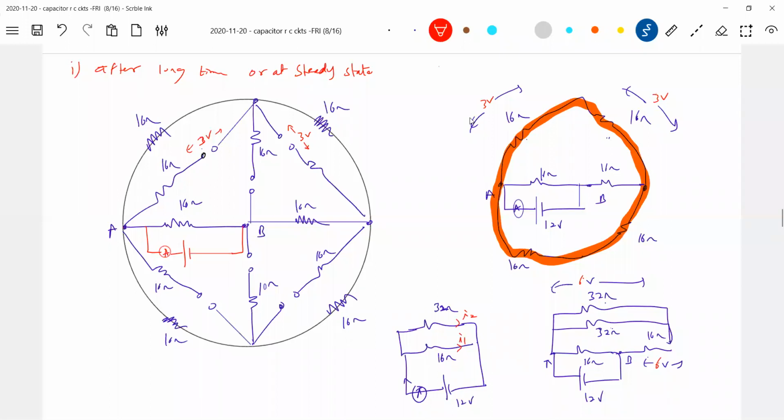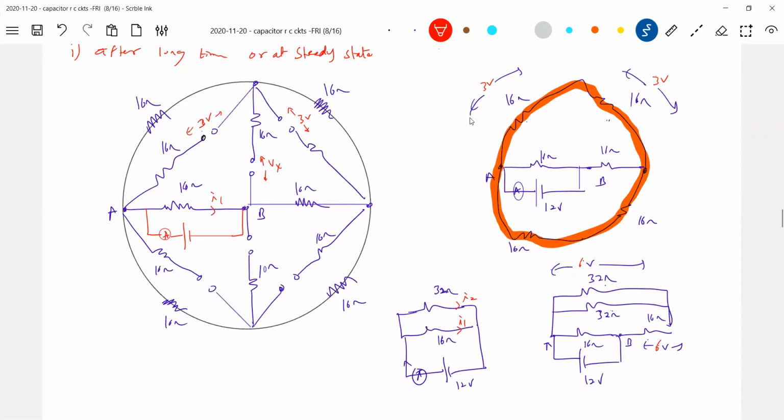It is forcing us to think a lot. That is the problem. Okay, once you know this 3 volt, now you can calculate this particular voltage. Call it V1, whatever you want, you can call this one VA or Vx. Write the loop equation, and you know this current I1. So this should be -3 minus Vx plus 6I1 equal to 0. Solve for, you know, I1 from here, you'll get Vx.